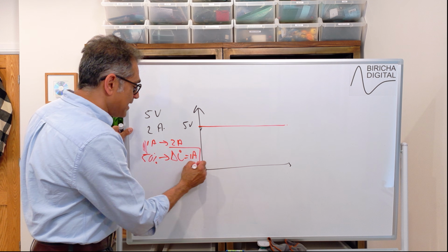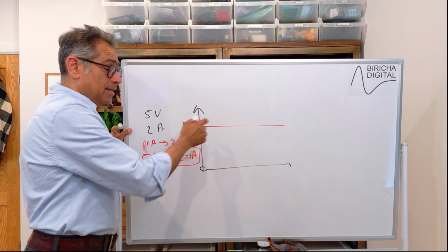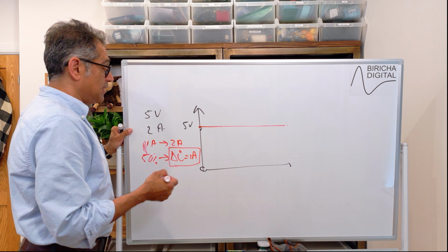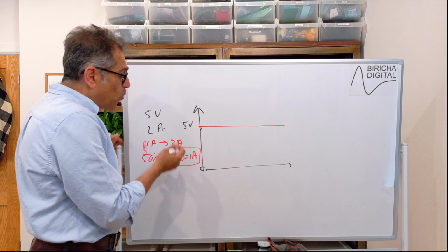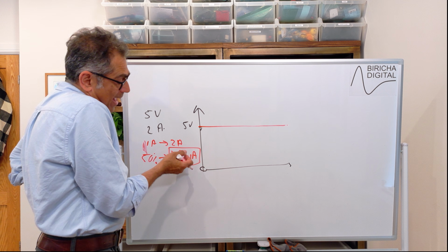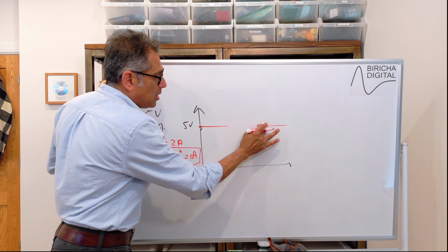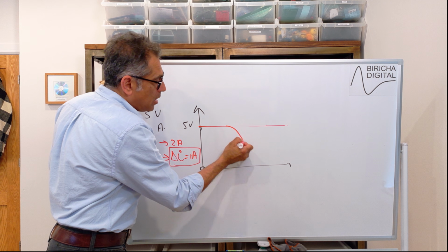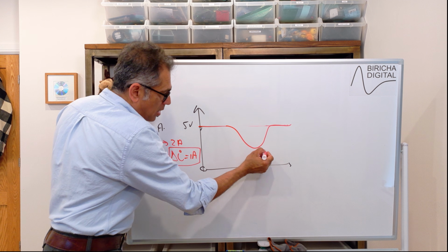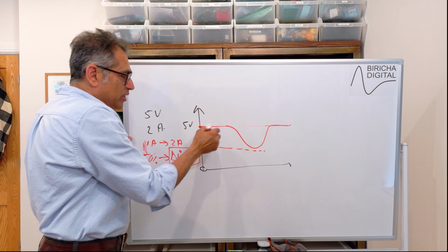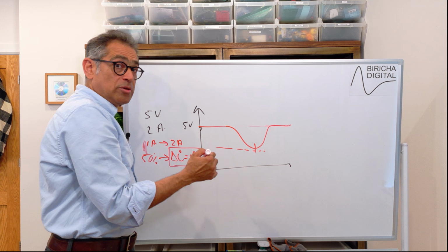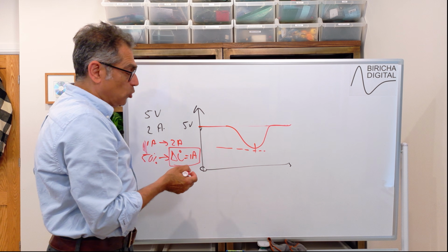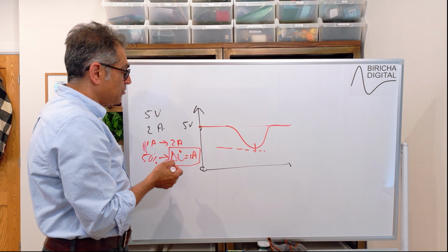I'm going to need that in order to calculate the size of the capacitor that I need. Then, let us also say that when this 1 amp load step occurs, I do not wish this output to fall below a certain level until the control loop starts to react.